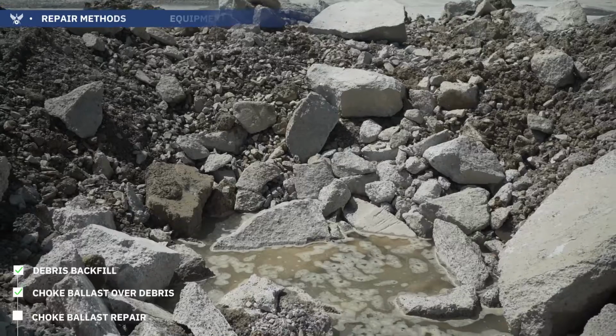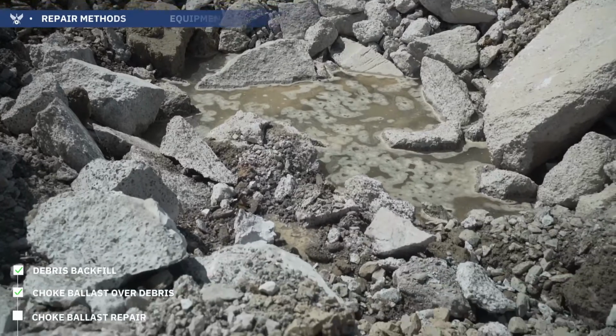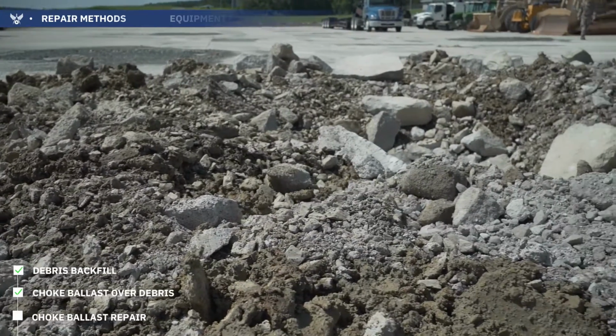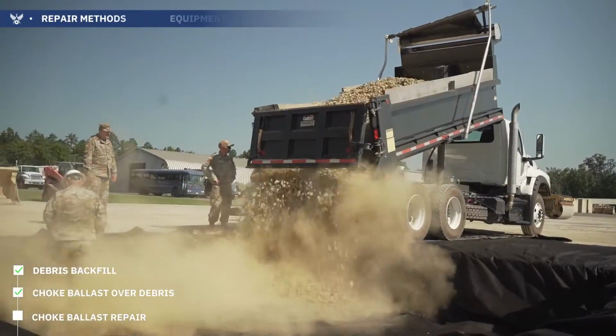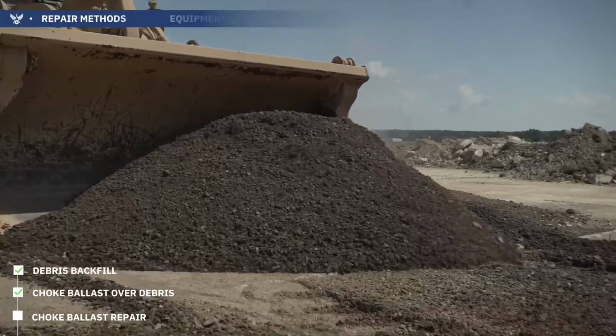Choke ballast repair. Used when water is standing in the crater or if subsurface material is unsuitable for filling the crater. Fill the crater with ballast rock up to 18 inches below the pavement surface. Fill the remaining portion of the crater with crushed stone.